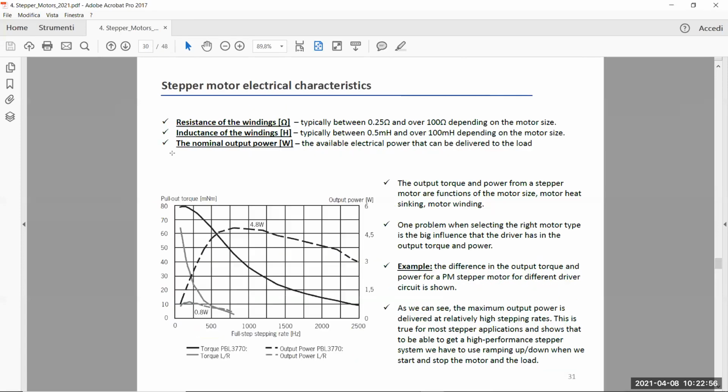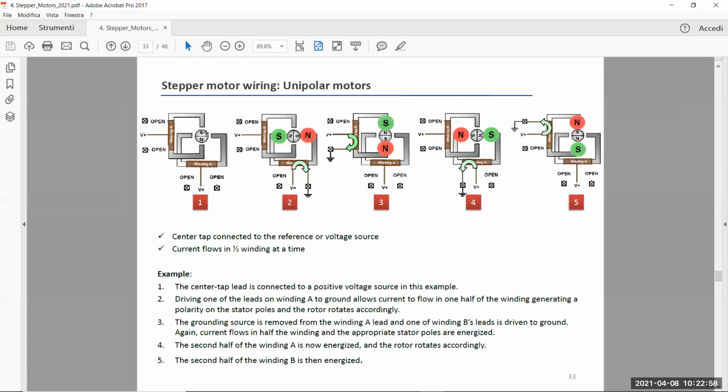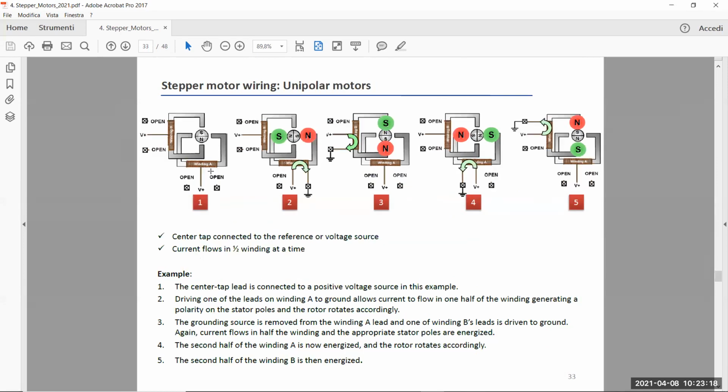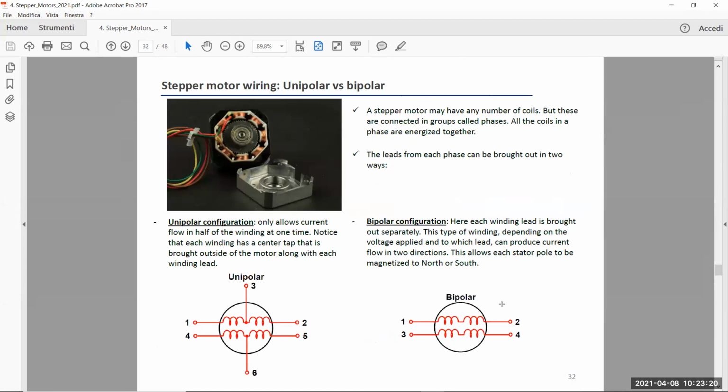This is the configuration. You can see the rotor here, which is the circular shaped rotor with 2 poles, north and south. Then you have the stator. There are these 2 big C shapes here, ferromagnetic material. Then you have the winding here. Each winding is bipolar in the sense that you have just 2 terminals, A and A prime, B and B prime, exactly as indicated here.